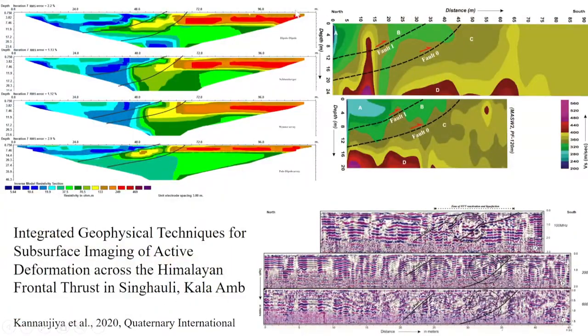So you can see this quaternary formation. As this is alluvial, it is mainly dry, and water content is very less. You can see the high resistivity, which basically demarcates the Shivalik, and where the resistivity is low, you can see the water saturation is more. Also you can see the typical change in the lithological resistivity contrast, and this resistivity contrast is nothing but due to the lithology change.